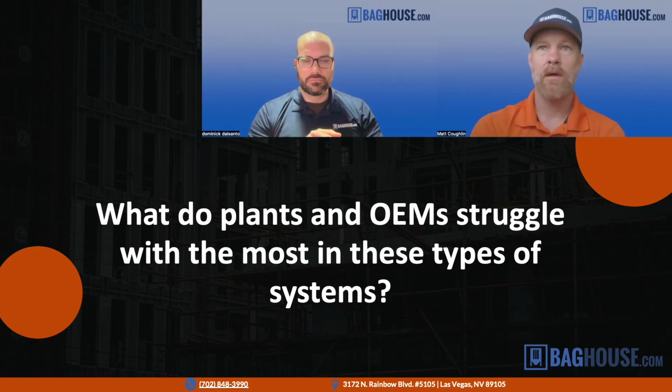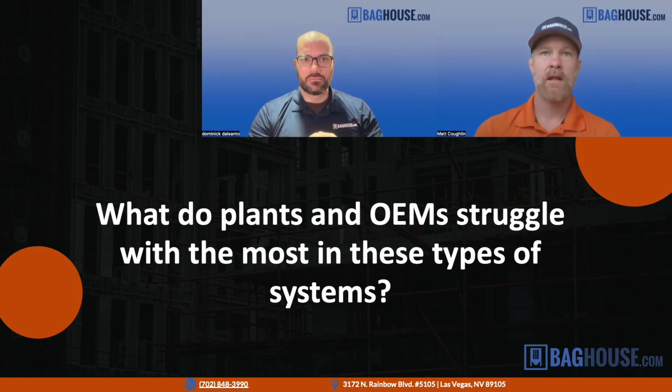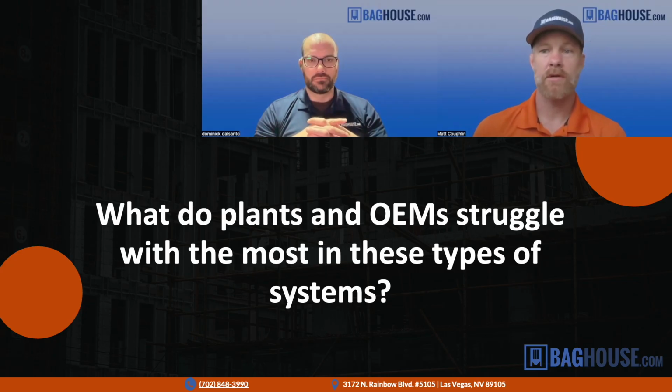And then over time, these types of facilities have a way of changing. Processes get moved around, pickup points get added, often for good reason, right? Because you have a new machine over here, you need to reroute this ductwork over there. We'll go into these facilities where the dust collection system may have been perfectly designed to start with, but things have changed. Ducts have been added, pickup points have been added or moved or closed off. And then you have balancing issues in the ductwork. You've added pickup points and watered down the airflow at each of the pickup points where you need it, and people are left scratching their heads as to why it's so dusty in the facility.